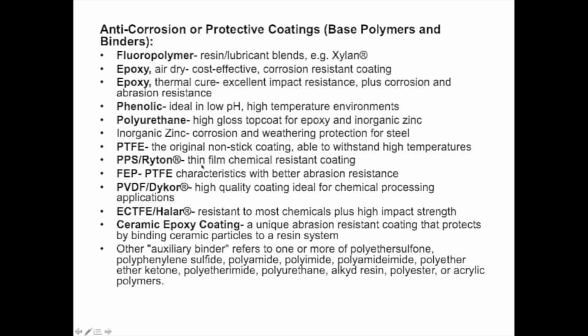high-performance polymers that produce basically a protective barrier or a thin film, or what I call hermetic sealing, that prevents diffusion of the corrodant, which could be oxygen or moisture, through that barrier and then prevents it from getting to the carbon steel surface or the steel surface that you're trying to protect. So this list here is not exhaustive, but just gives you a representation that protective coatings are tougher materials, more expensive than your typical acrylate, polyurethane, or even polyester resin.